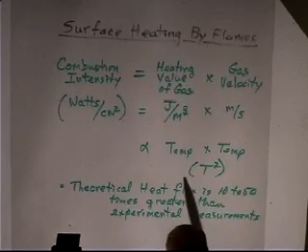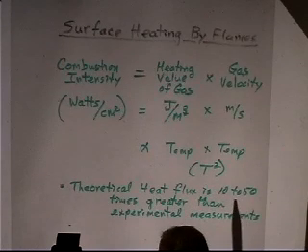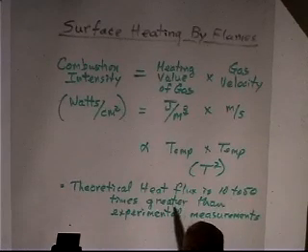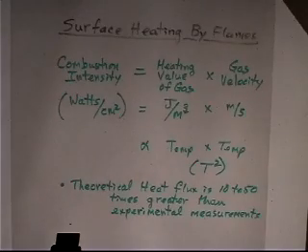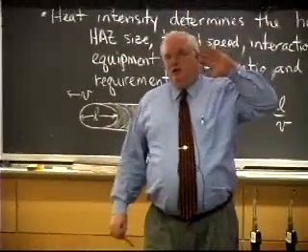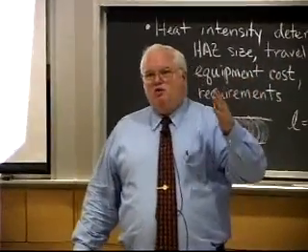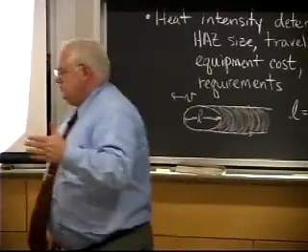So the higher the temperature of the flame, the better off I am. We also find, and we'll discuss this in a little more detail in a little bit, the theoretical heat flux is 10 to 50 times greater than what we measure experimentally. Now, we actually said that the other day when I was talking about heating efficiency. And I said that the heating efficiency down at 1,000 watts per square centimeter is only about 2 to 10% efficient.